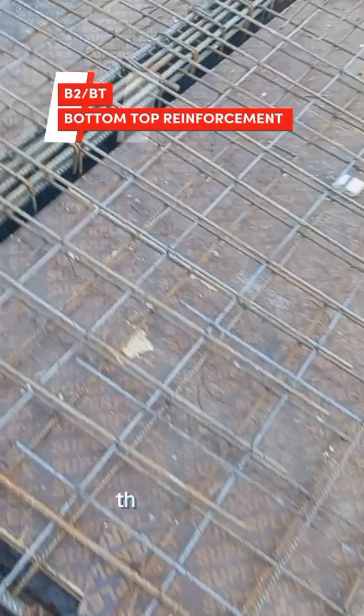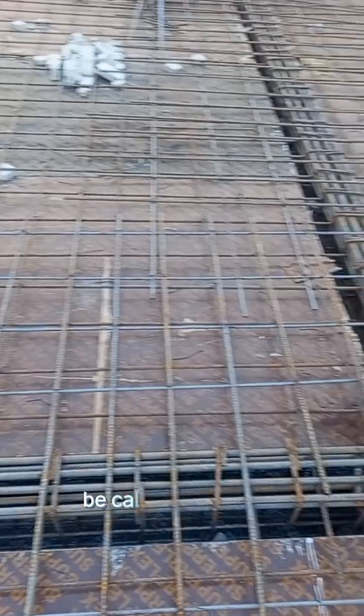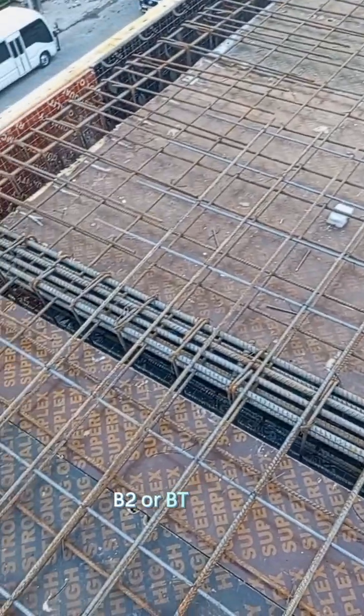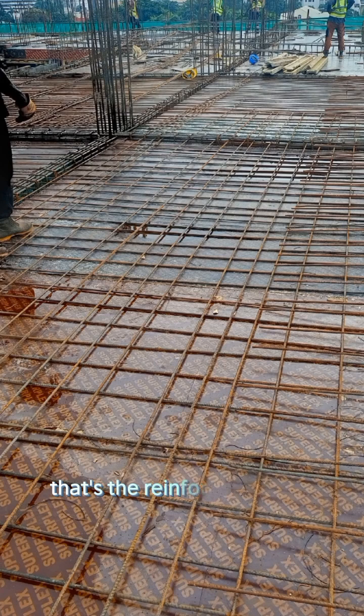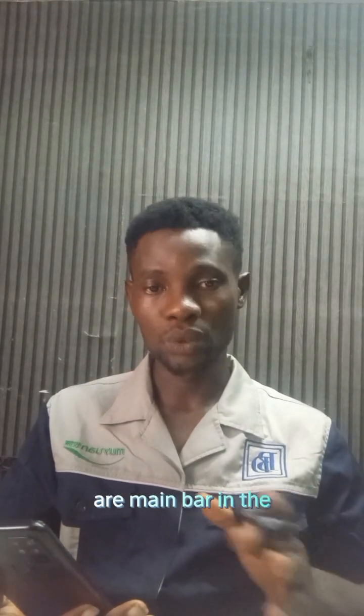Now then we go to the B2. The B2 is the reinforcement on the B1. The B2 can also be called bottom top. That is, you can call it B2 or BT, that is bottom top. That is the reinforcement on the top of the B1. Now this reinforcement is a distribution bar in a one-way slab. But in a two-way slab, it is a main bar. That is, the B1 and the B2 are main bars in a two-way slab.